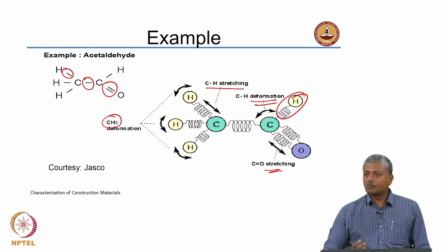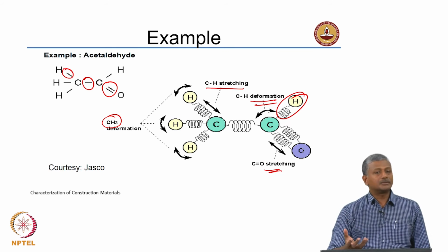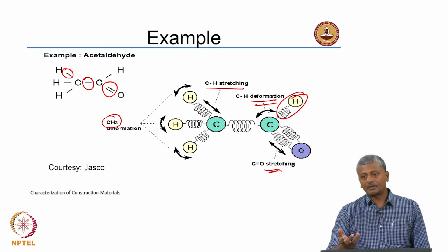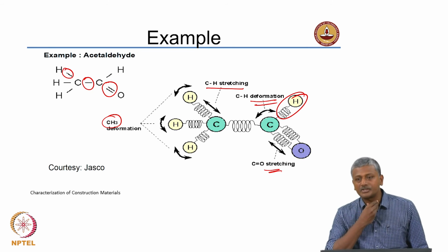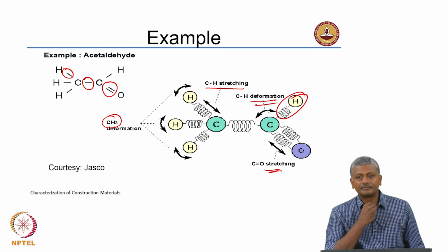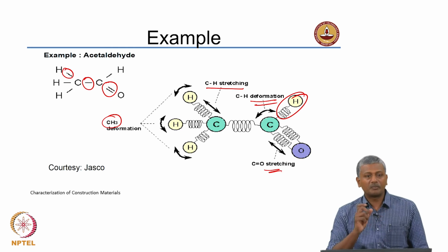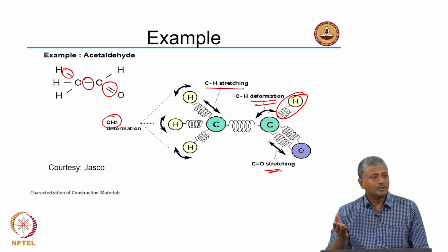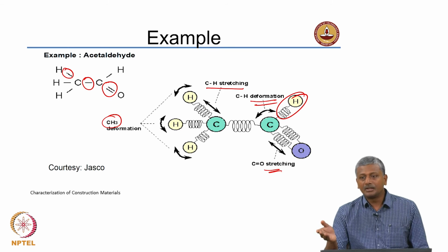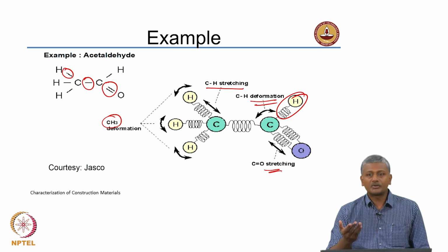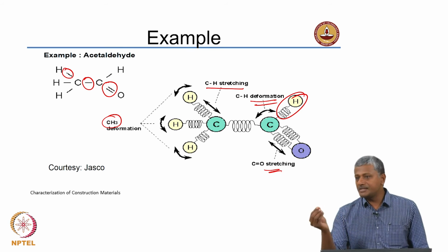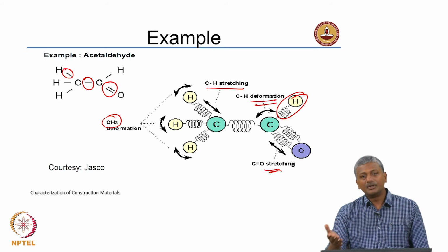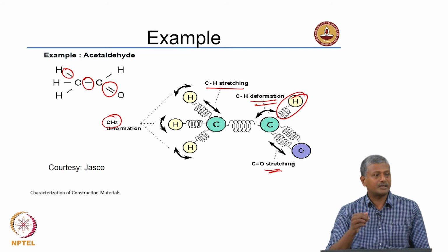right. So, with this what we are trying to do is deciphering the structure of the molecules that we are interested in. Now, in the case of cementitious materials, what would you expect to see? What kind of bonds are there in cementitious materials? No, what sort of bonds? Between what elements? You have SiO, then aluminum oxygen, right. You may get carbon and oxygen from carbonate species that are present in the system, right. Then you have OH, oxygen and hydrogen, and so on. So, for each of these specific bonding systems you will get a signature as far as your FTIR spectroscopy is concerned.